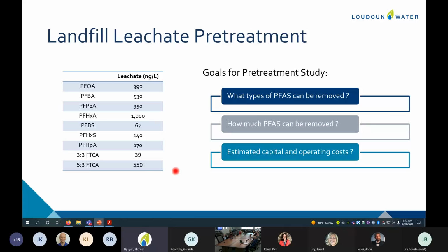So for example, when the health advisory came out for PFOA for drinking water, they said PFOA should be limited to 0.0004 nanograms per liter, right? But for PFBS, they said the health advisory is 2,000 nanograms per liter. There's a huge difference in those numbers because PFBS is a short chain PFAS.